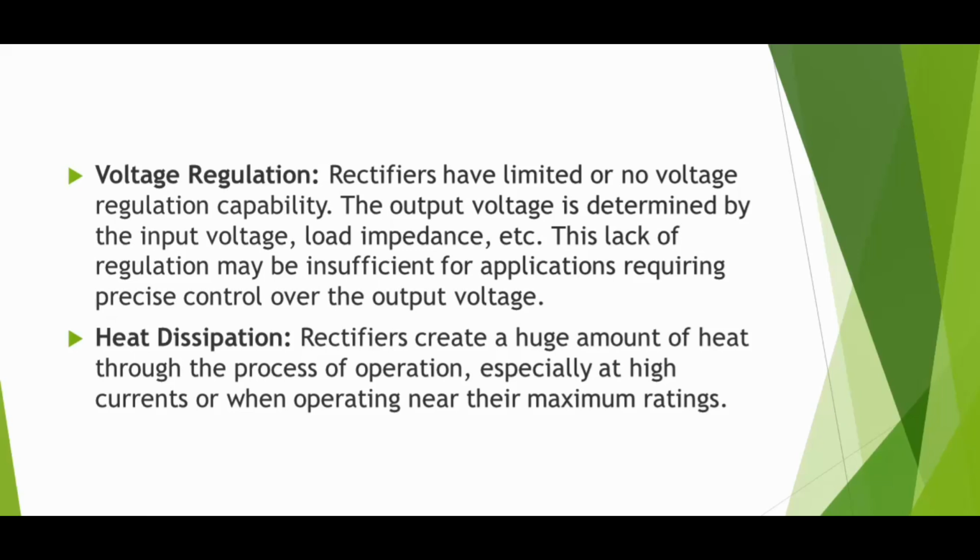Ripple factor is high and an elaborate filtering is therefore required to give steady DC output. DC saturation of transformer core resulting in magnetizing current and hysteresis losses and generation of harmonics. These are the main disadvantages.